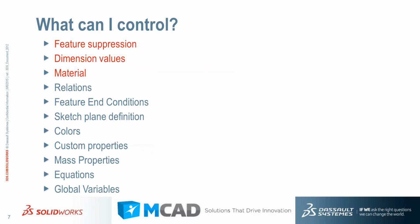So what can you control with a configuration? Well, when I started working with SolidWorks, you could only change dimensional values and suppress and unsuppress features. But now you can see that list is quite expanded. We can configure materials and relations, end conditions of features, what sketch plane you're sketching on, colors, properties, even equations and global variables are now something that is configurable inside of SolidWorks. The top three, though, are still the most commonly used. That's what I see more than anything else.